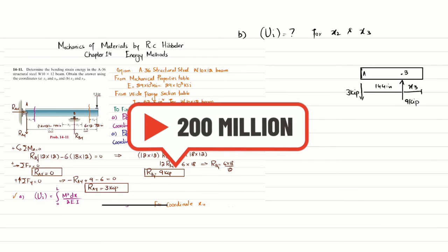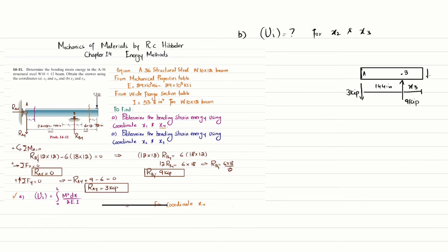So when you cut it, you will have a shear force V3 downward, and you will have a moment M3. This is your point 3. So we'll find this moment by using the equation of equilibrium. The first equation of equilibrium is that the sum of all moments about point 3 is equal to 0, taking the counterclockwise moment as positive. So about point 3, one moment is M3, which is counterclockwise. So I will write M3.